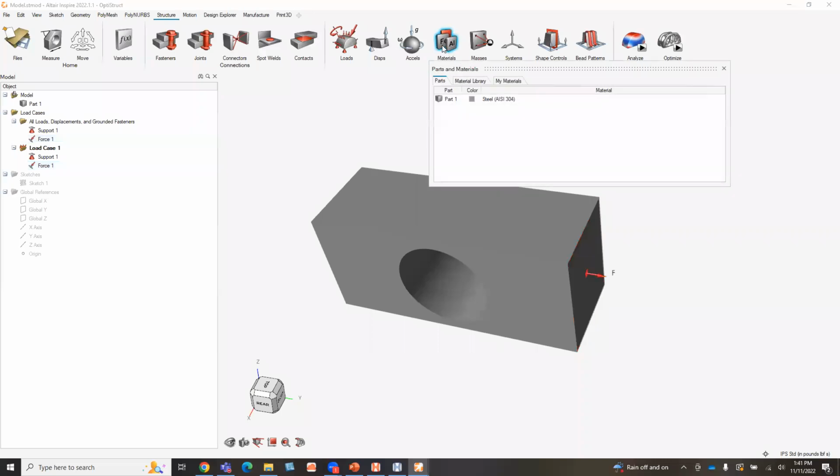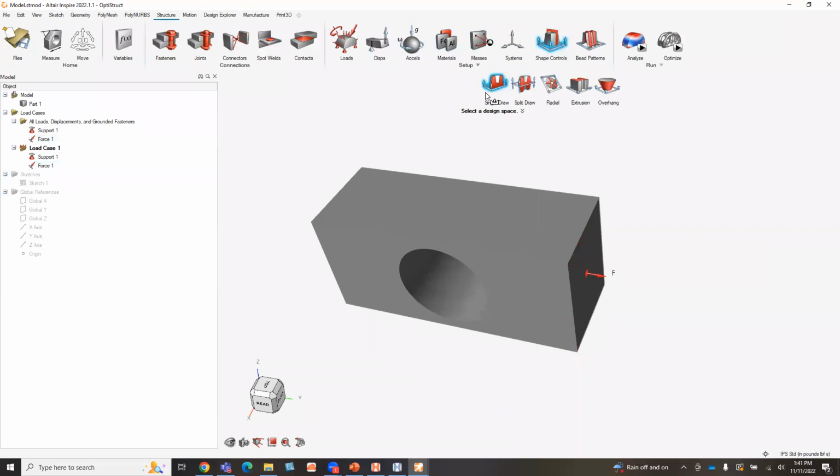In Inspire, we can specify our materials, and then we can specify some of the cool manufacturing controls when you run optimization. One of the things we do a lot is work with DFAM, but also subtractive manufacturing. If you need to maintain a constant extrusion, we can specify that when it removes mass from the system, because what topology optimization is doing is removing mass.